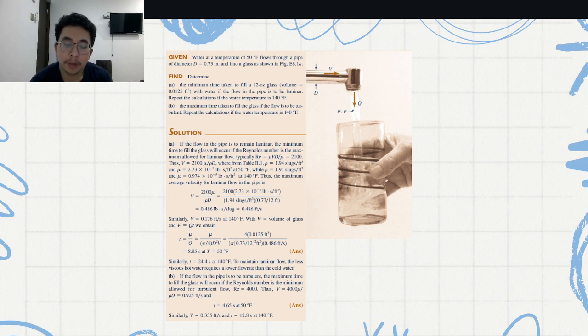I got this question from the book, and I think they use a reference of a maximum Reynolds number for laminar flow of 2100. It's fine. You can define it wherever you want. It's between the 2100 and 2300 range, but 2100 is okay. So the max is 2100.